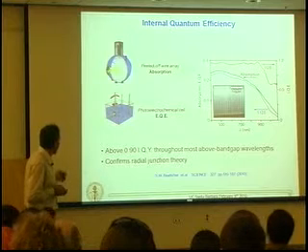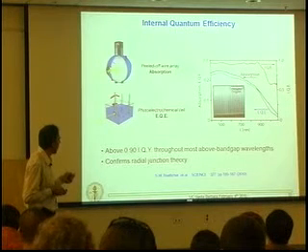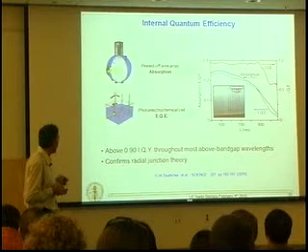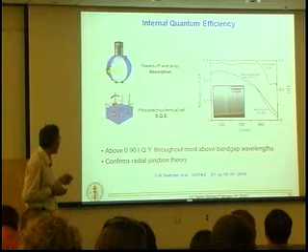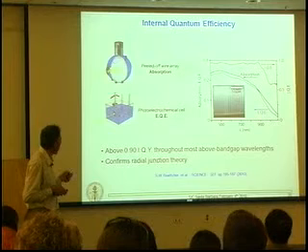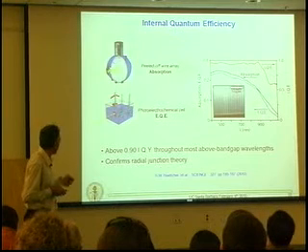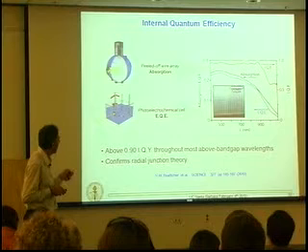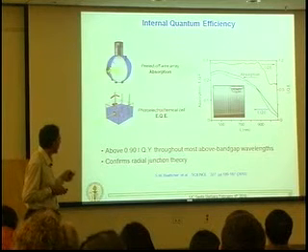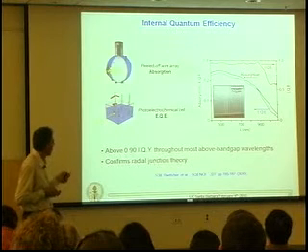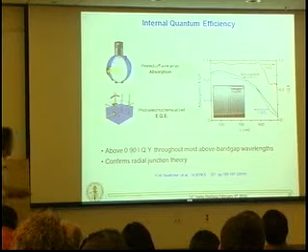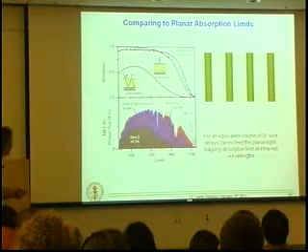The wires themselves still have excellent internal quantum efficiency. These are measurements of the internal quantum efficiency made in a photoelectrochemical apparatus. We have similar measurements using transparent conducting oxide contacts. And while the absorbance of this structure fell off because we didn't have the textured back reflector, we can measure the absorbance and the photocurrent, the ratio of which is the internal quantum efficiency. And you can see here, until we get close to the silicon band edge, it's very high. So these are good photovoltaic collecting junctions.